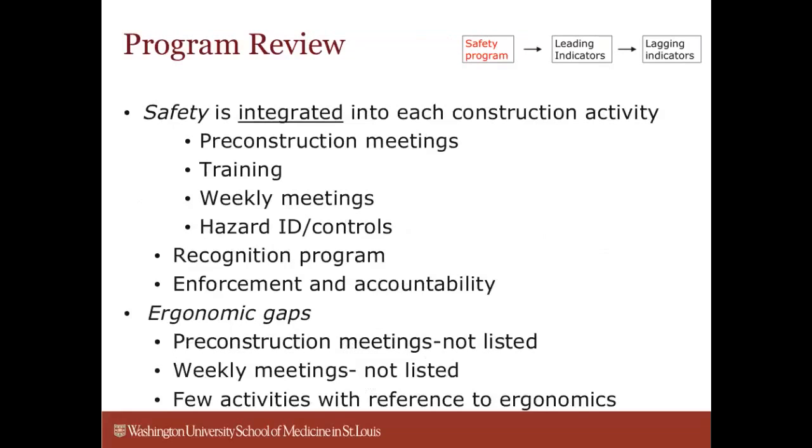And what they found was safety was integrated into each of the construction activities. And here by safety, I'm primarily referring to the Focus 4. So they identified falls, struck-bys, confined space, and electrical hazards and controls in all of their safety activities: pre-construction meetings, training, weekly meetings, hazard identification and controls, the recognition program, and they had enforcement and accountability for all of those safety risks.